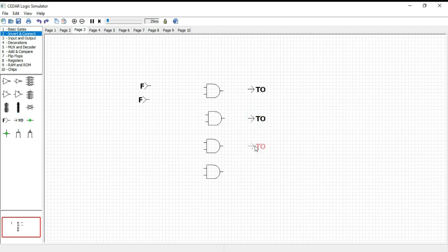Okay, fine. Now I want two NOT gates to build this 2 to 4 line decoder. So I go to invert and connect and select the small inverter as my NOT gate. Okay, I want two small inverters. Fine. Now let's build our decoder by using wires.